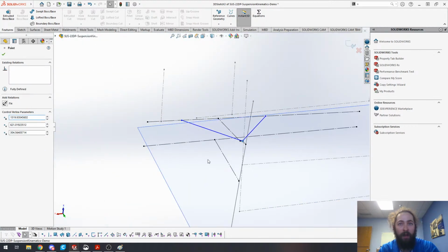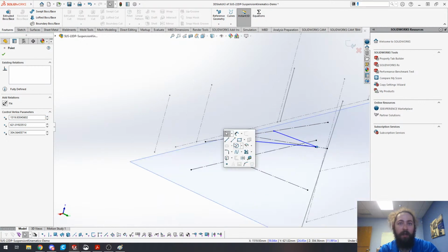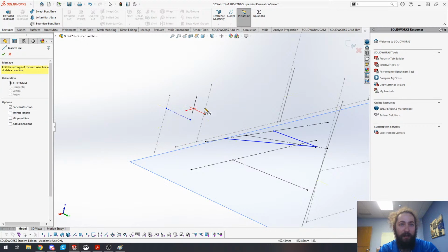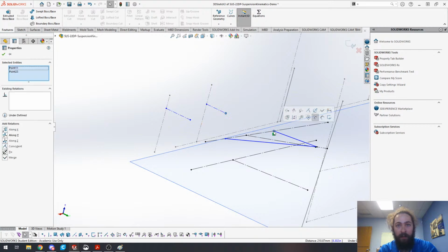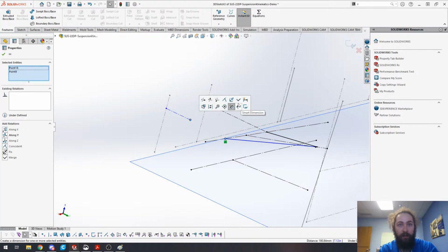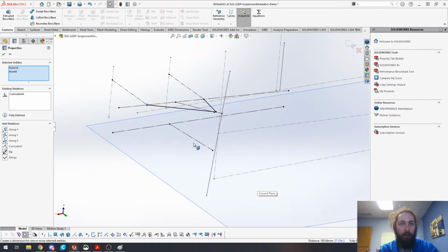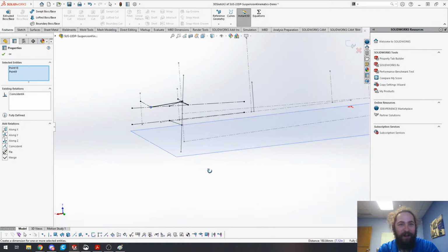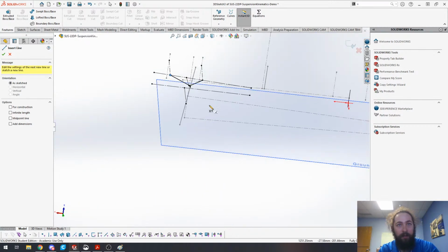Now we have to figure out where our inboard points are, and that's where this chassis side constraint sketch comes in. Basically, we make a couple of lines along the y-axis. A couple stubby lines there. Then we merge these 2 points. And same thing here. Merge those 2 points. There we go. We've successfully created our first control arm. An hour and 55 minutes in. All right, so same thing on the bottom. A couple of lines on the XY plane.